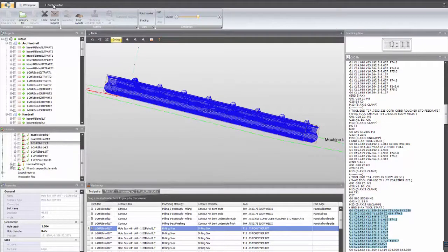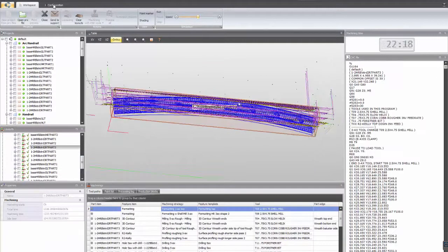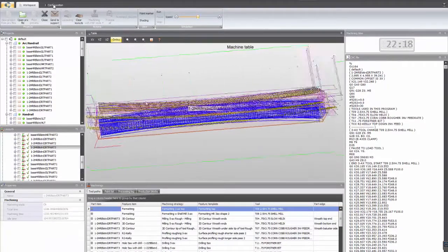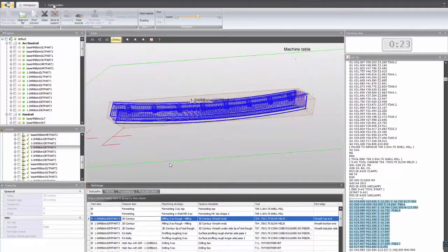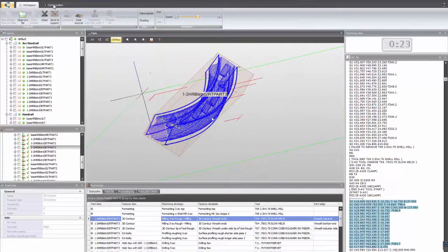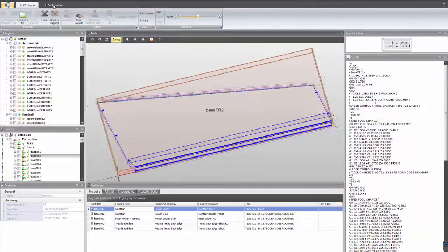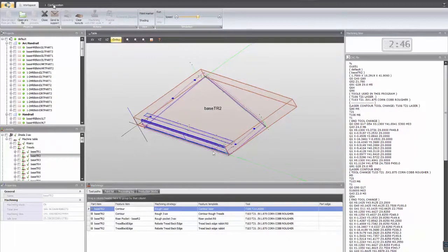I can go down to wreath parts. Here again, here's all the tool paths. And again, these are cut and drilled for balusters to cut through the tangent of the rail for the tangent handrail method. And these treads are a different profile than what we just showed you. So this is actually a 1 3/4 thick tread.